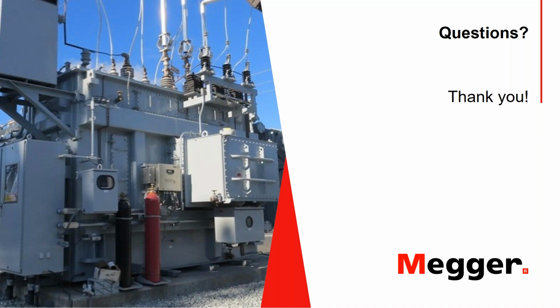Once the measurement is complete, that energy has to be discharged, right, to be safe for the user to swap connections if needed, or to simply disconnect when finished. So the important part here is that discharge process. A DLRO is not designed to do so. It won't have the proper circuitry to discharge that energy.